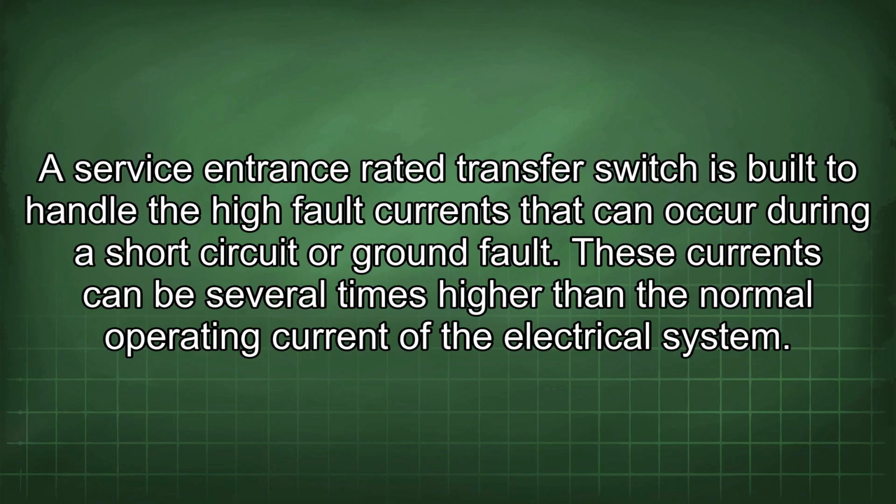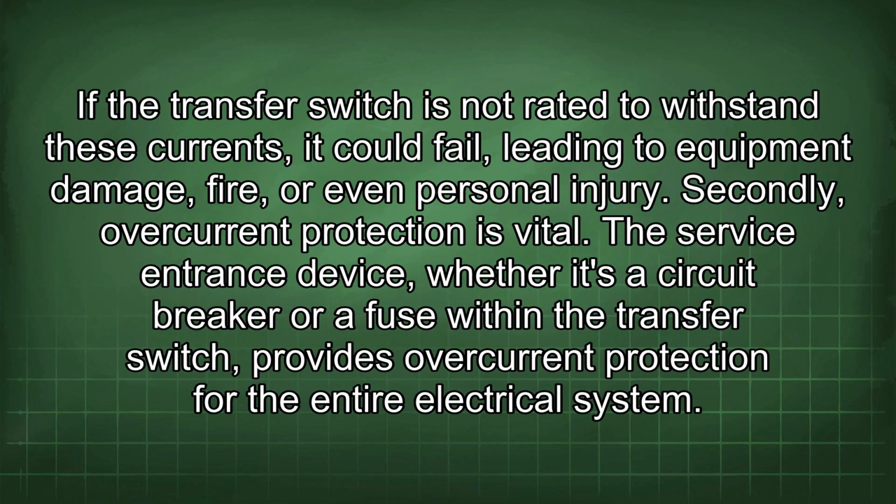A service entrance rated transfer switch is built to handle the high fault currents that can occur during a short circuit or ground fault. These currents can be several times higher than the normal operating current of the electrical system. If the transfer switch is not rated to withstand these currents, it could fail, leading to equipment damage, fire, or even personal injury. Secondly, overcurrent protection is vital.